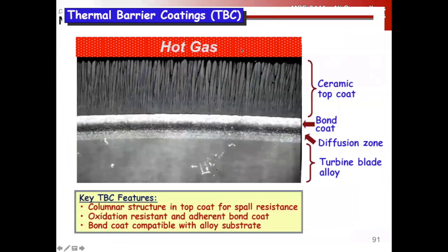And the other is thermal barrier coatings. This is what I did when I was at Pratt & Whitney. I can tell you right now, this is applied by electron beam physical vapor deposition, EBPVD. Thermal spray is the other primary way of doing this, but EBPVD gives you these nice columnar grains so you don't have issues with thermal expansion mismatch, right? Because these grains can handle a lot more strain in this direction than a solid thermal spray coating can.